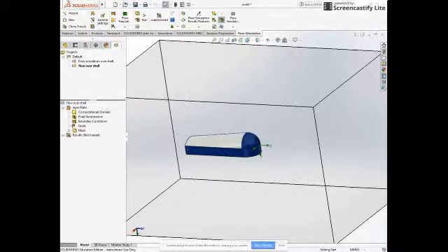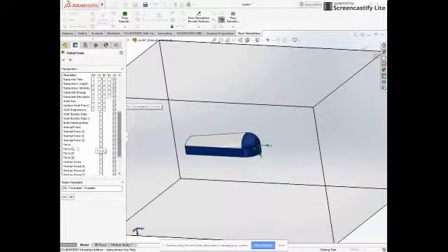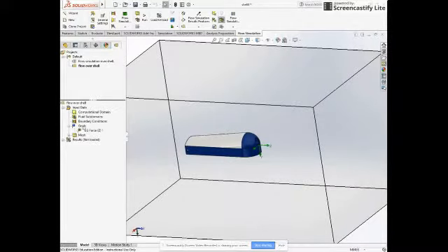The next thing with this model created, we're going to want to set some goals. The first thing is to insert a global goal. What we're going to be looking for is force, and that's going to be in the Z direction here. Click that and click the goal.